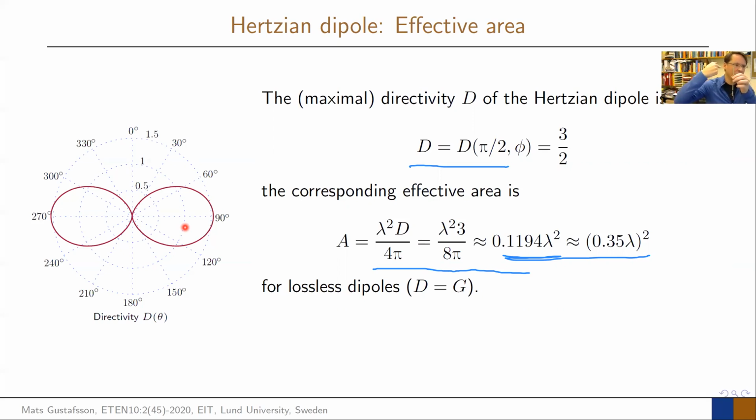It's missing the antenna, but somewhere it gets sucked up into it. So in some ways, this perfectly matched small antenna has a size of 0.35 wavelengths times 0.35 wavelengths, and it basically collects everything that comes inside of that. That is what happens when you go for a small antenna compared to a large antenna. They can have some very mysterious properties.